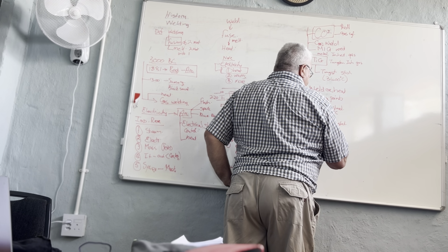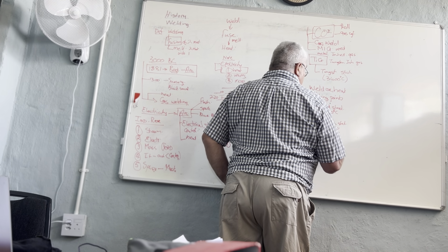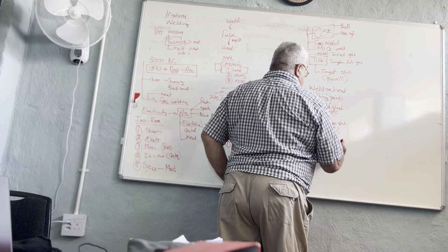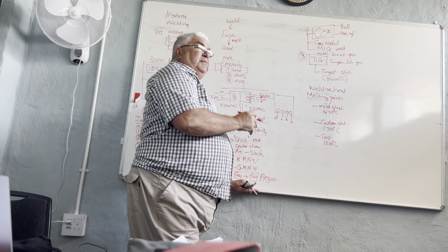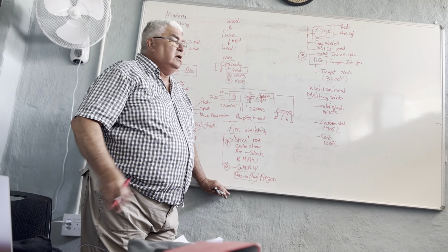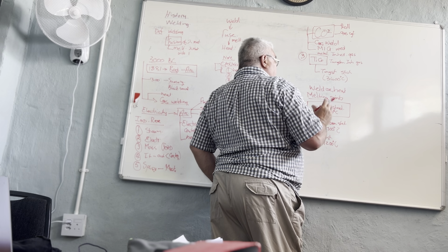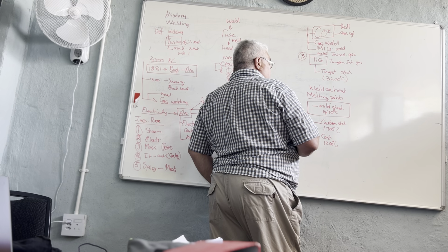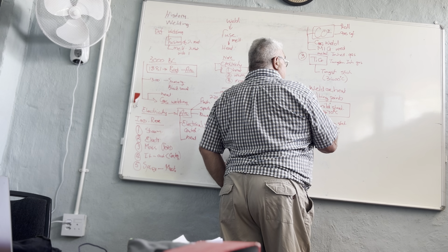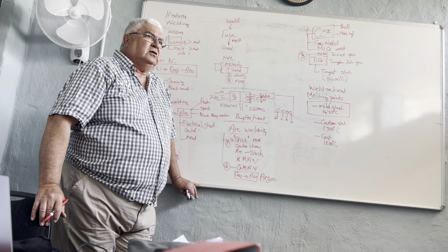That melting point can go up to 1700 degrees Celsius. Cast iron, which I will come back to, is a special one, melting at 1200 degrees Celsius. Let me put a few others that are not relevant now, but we will get to our material classification in more detail. For now, just know that our limitation right now is commonly mild steel and maybe high carbon steel. I might have stainless steel that's also got a higher temperature, but these are the common ones that we're using. And that's one of the limitations of arc welding. It can only be applied to a selected group of materials.